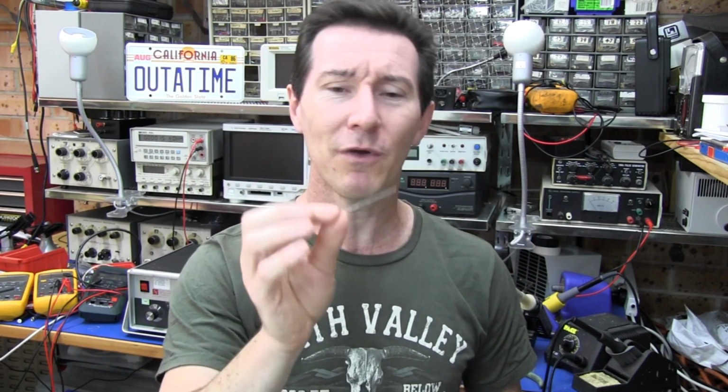Do they manufacture 10% tolerance resistors and measure them and then mark these ones and sell these ones as 1% and sell the other ones as 5%, sell the other ones as 10%, etc.? How do they do it? They don't really tell you on the data sheets, and getting info on that sort of thing is hard. So just what is the probability distribution, that's the technical term, of the values of a typical resistor like this? You can't really find it in the data sheets.